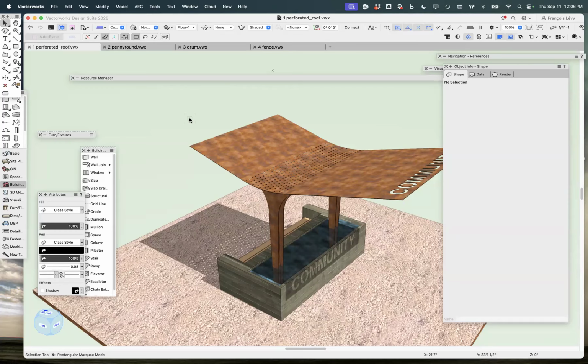If we go into it, you can see it's just a circle that I've extruded by an inch, just some arbitrary value. It needs to be enough of an extrusion to penetrate through the plate steel. So it's a circle 1 inch diameter, extruded an inch, and then I made it into a symbol. And that's important, and I'll show you why in a little bit.